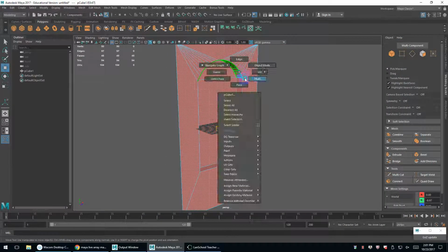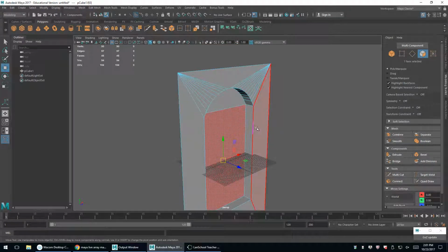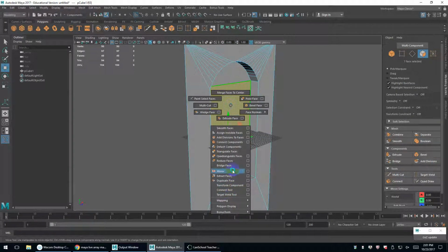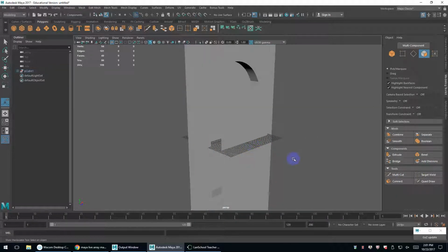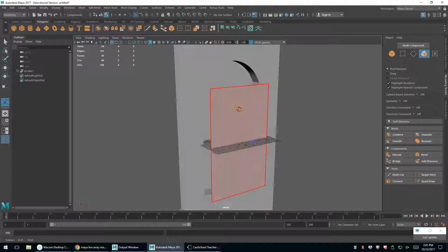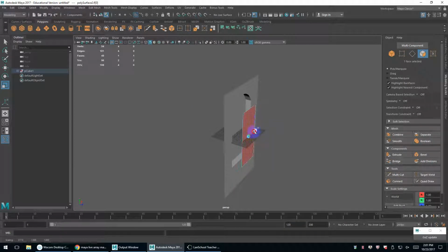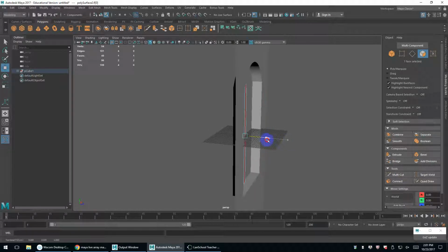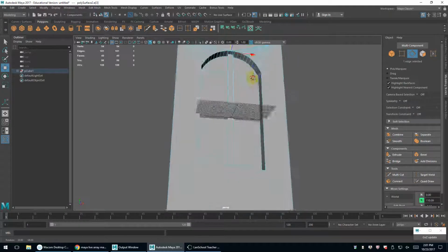So if you're building framings and stuff like that, what I often do is I keep building off of what I've already done in a lot of cases. So I'll shift right click and go to duplicate face, which actually creates a separate object. So I'll pull this plane out in front, click off of that. Now I've got this plane. I'll take the plane and scale it in, right? And I'll push this back. So this is still technically a separate object. I'll grab this edge up here, move this up like so, just so there's a bit of overlap.